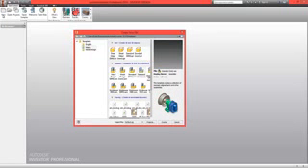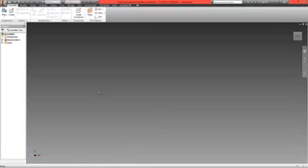In this series of videos we're going to learn how to build a VEX tumbler using Autodesk Inventor. To begin with, from the ribbon select New, and from the pop-up we're going to select a standard assembly part which is labelled .iam. Select Create, and what we've now created is a new assembly part.